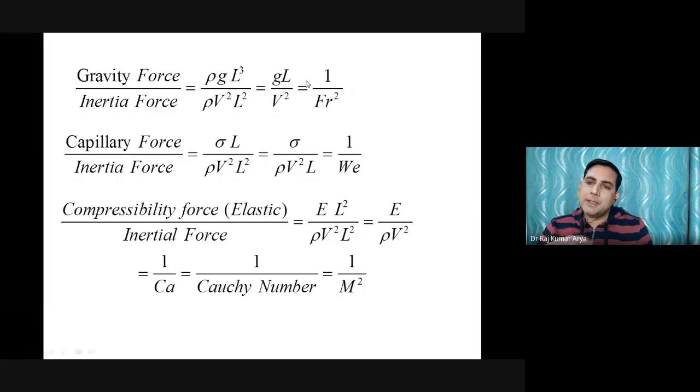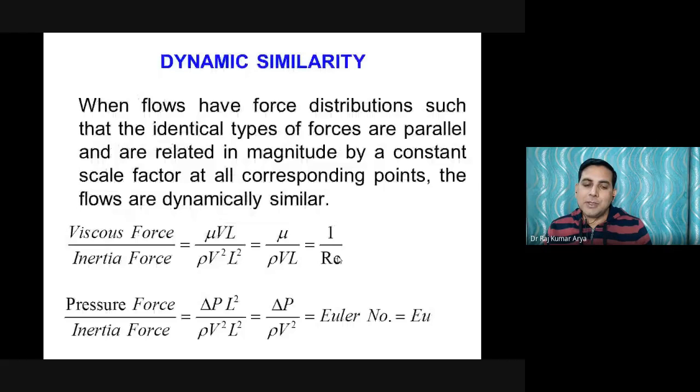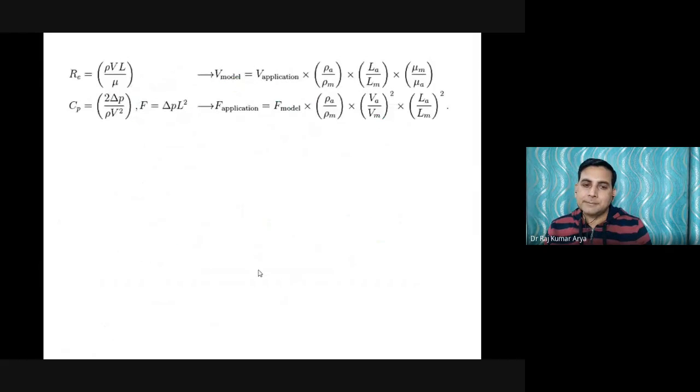If you are putting some external force from the outside, then the surface tension, your capillary rise, your diameter is too large, then capillary doesn't play the role actually. So the capillary number and the Weber number should also not be considered where surface tension is not a dominating force. So most of the time you are ending with the Reynolds number, which is the major number that needs to be considered in most cases. So that's what we have here.